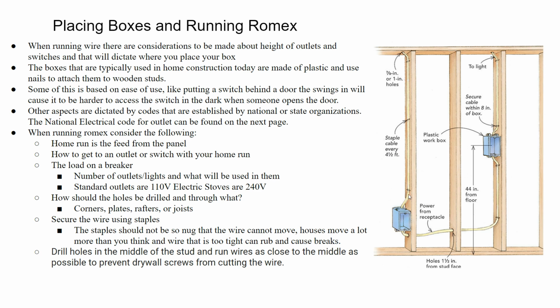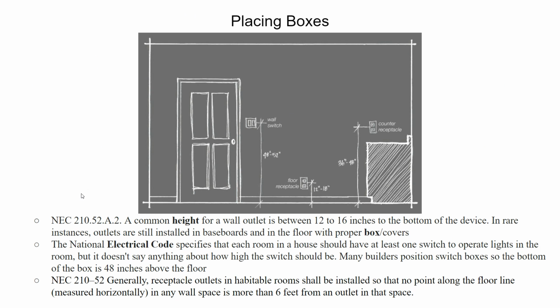You're going to staple the wires to the studs. You can see this is our wall. That'll secure them. You don't want to pound that staple in so far that it cuts the wire. That's bad. And then on top of that, you want to make sure that there's a little bit of give there, because guess what? Houses move. And when the house moves, you don't want the wire pulling and cutting and being abraded by that. So this is coming directly from the National Electrical Code.